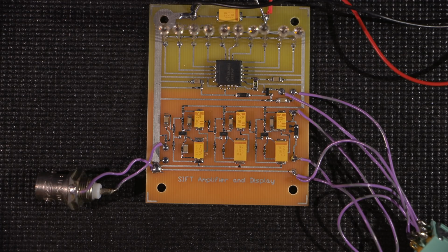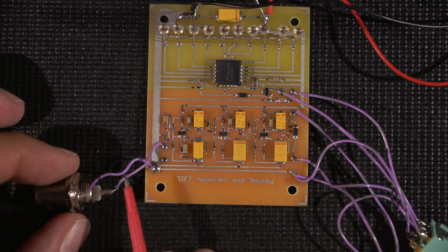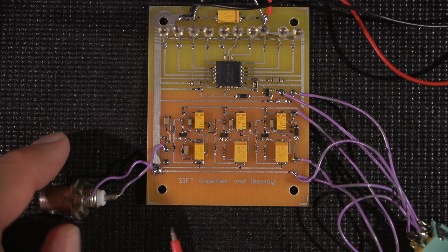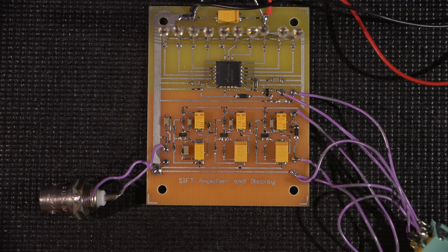If your scope has the ability to do 50 ohms or 1 megohm, of course you're going to want your input on 1 megohm, right? Now, if you're looking for an extremely low level signal, you'll find some oscilloscope probes out there that are ×1 and ×10. ×1 would be the preferred setting for a very, very low level signal. If you're ever using a ×1 probe, be very careful with the input of your oscilloscope. You don't want to hit any high voltage DC or anything on that ×1 probe.